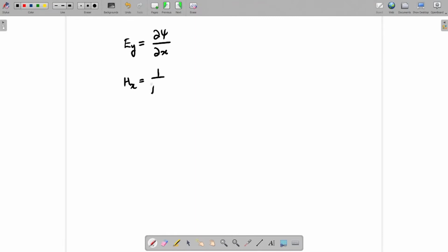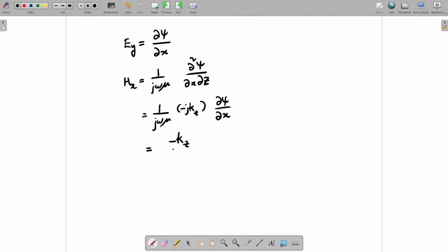E y is del psi by del x, H x is 1 by j omega mu del square psi del x del z, that is 1 by j omega mu times minus j k z del psi del x, that is minus k z by omega mu E y.